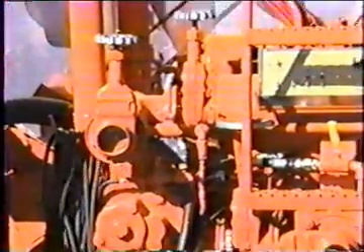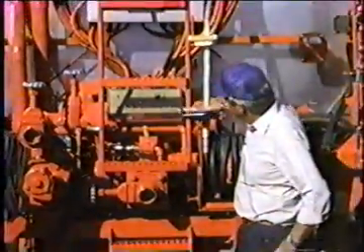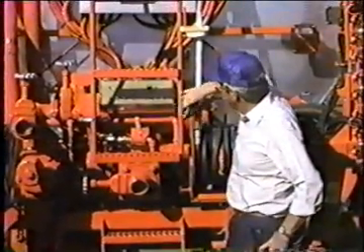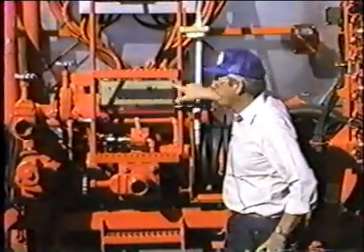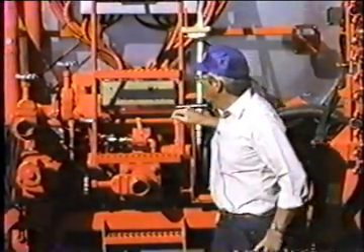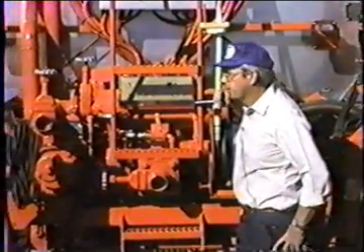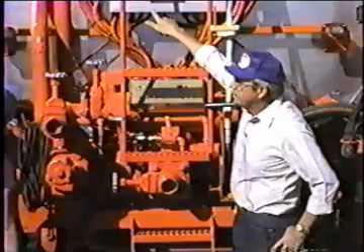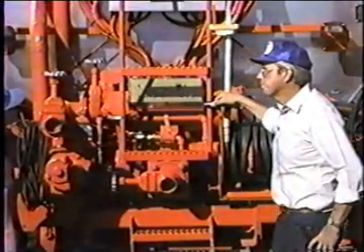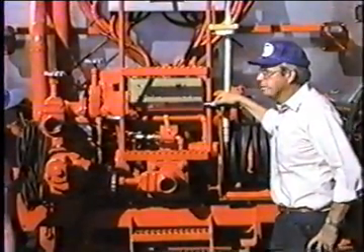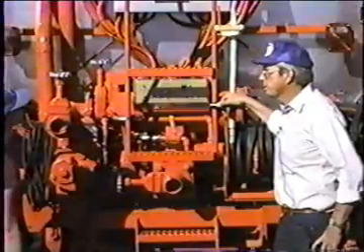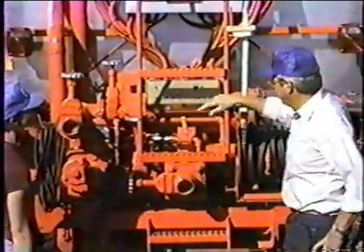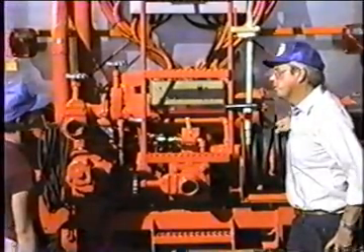This valve on the handgun itself, when it's crossways with the gun, is in the closed condition. If we open it like that, that handle is open. Okay, the truck is circulating. It's going through the spray bar and freely going back into the tank through the relief valve there. Remember, the asphalt always takes the path of least resistance. In between those two there's 50 feet of 3/4 inch hose.